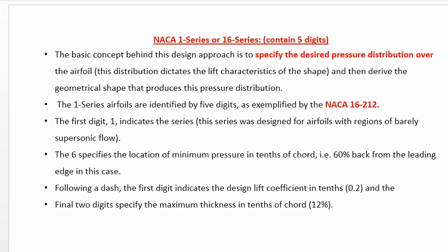Similarly, you must know why they developed this type of series. The basic concept behind this design approach is to specify the desired pressure distribution over the aerofoil. With the help of the pressure distribution I can find out my lift characteristic values. So for that purpose they developed the 16 series. This distribution dictates the lift characteristic of the shape, and then they derive the geometrical shape that produces the pressure distribution. That is why they developed the 16 series.